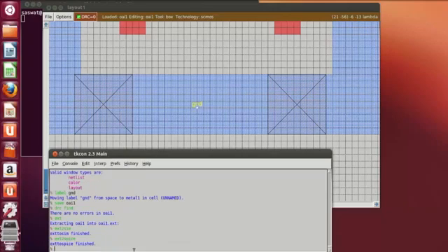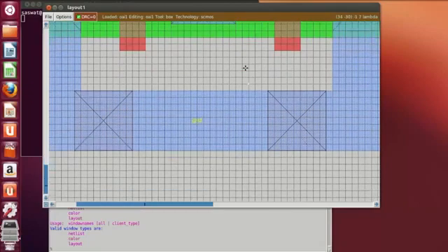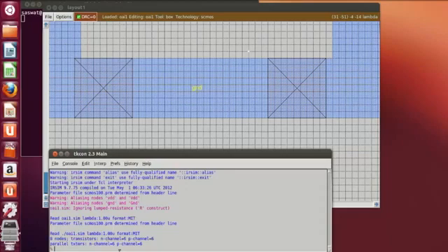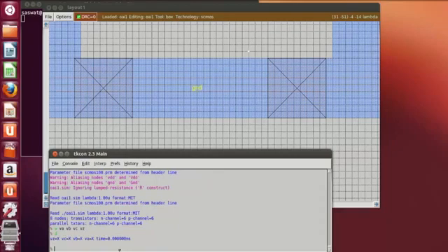Okay. Now after this, type irsim OAI1.sim. Now you want to watch VA, VB, VC and VZ. Enter D display. So all the values are X.